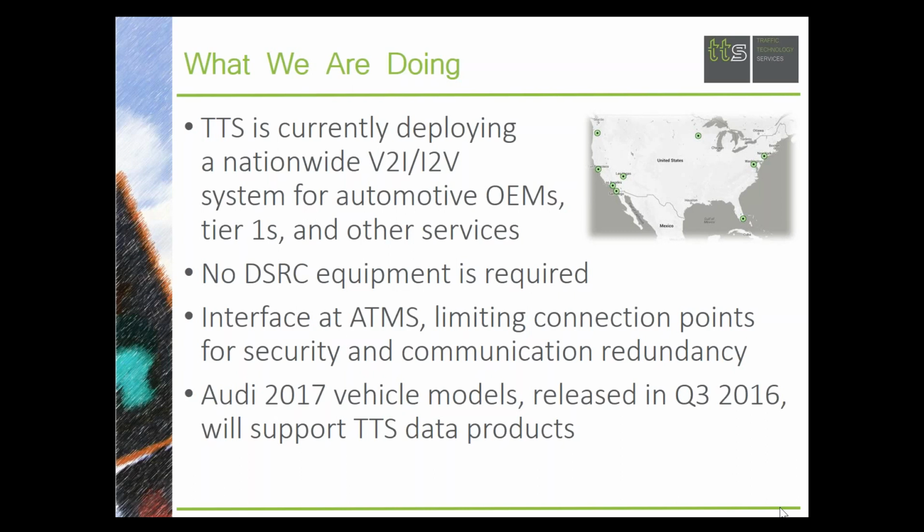As I mentioned, a key differentiator here is there's no DSRC equipment required, so nothing at the traffic signal cabinet. The actual interface is with the traffic management system. It'll be at the central controller at MnDOT Water's Edge. It'd be at Dakota County's shop, City of Minneapolis, etc. So it requires a system that is highly interconnected with fiber optic communications or other communications to get the data.